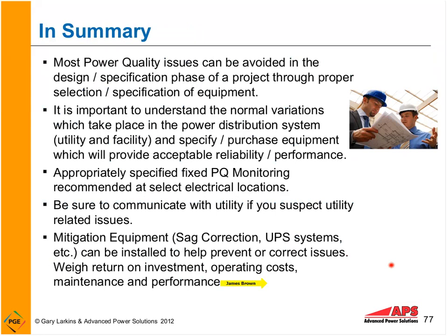I would highly recommend, if you have a facility or you work with a customer or client that has a facility, that they put power quality monitoring, fixed monitoring, in place. It's kind of like a gas gauge or temperature monitor on your car. What is happening on the system? What kind of events? What's the range of fluctuation? So later, if I'm going to go buy a new piece of equipment, I know what's happening on the system. So I can say, okay, this is the kind of fluctuations I need to be able to tolerate in my system.